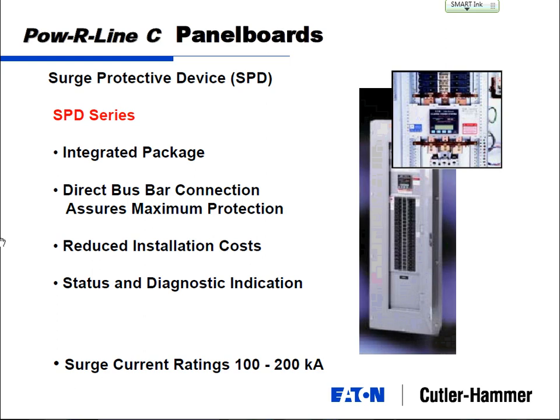You could have a third layer in between if you've got a big campus building where maybe you've got power distribution panels in there. Or always have this final layer where your computer is plugging into some type of surge strip, for lack of a better word. Surge strips, they're not great protection. They're just a fraction of the ratings of something you can put in the panel board, but it's a great last step of protection.